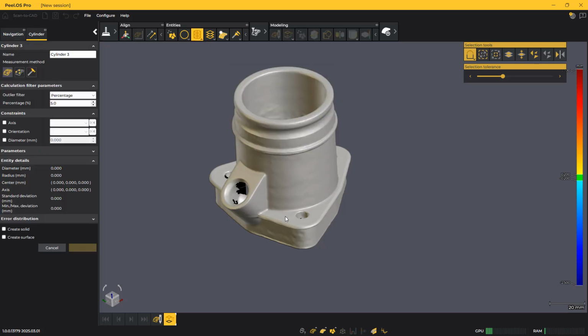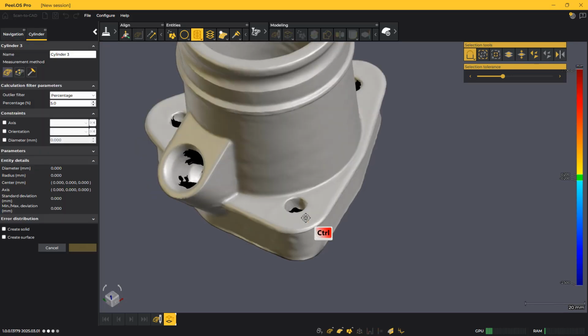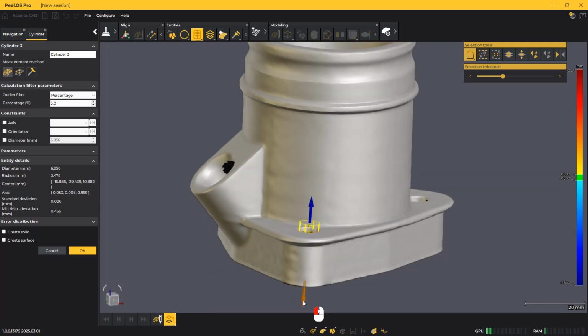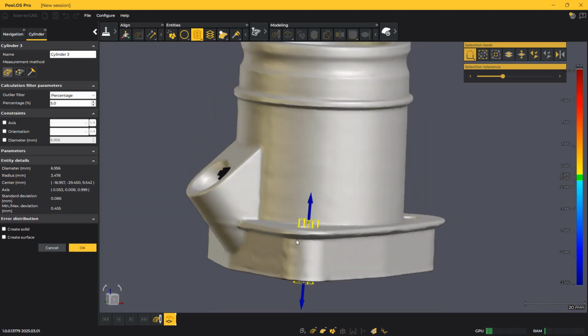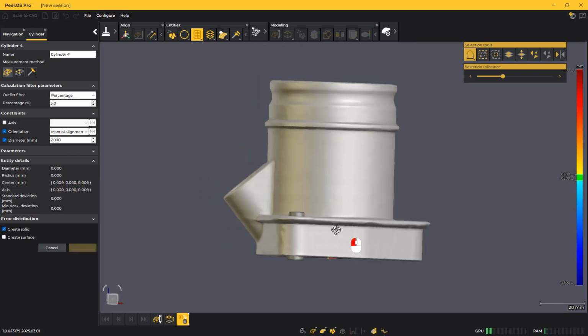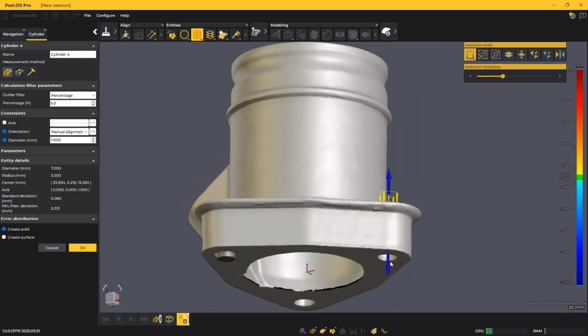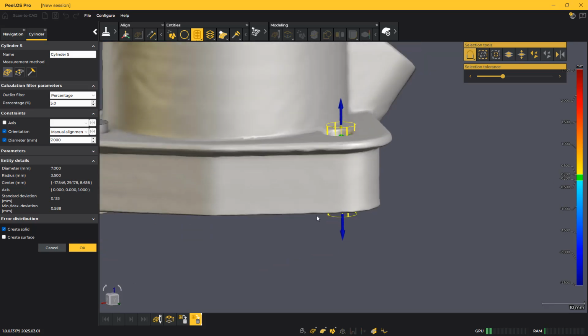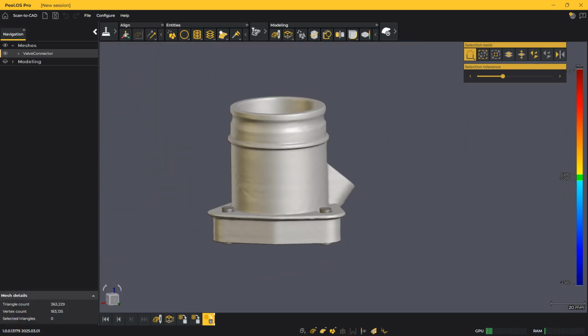Another useful option for modeling is the ability to turn 3D entities into surfaces or solids. In this example, we create a cylinder and ensure its orientation is parallel to the Z-axis. Then, we set the desired length and round the diameter to the extraction value. Once all the parameters are as wanted, check the Create Solid box to turn it directly into a solid. You can then repeat the operation with other similar entities, as the software will remember the settings.